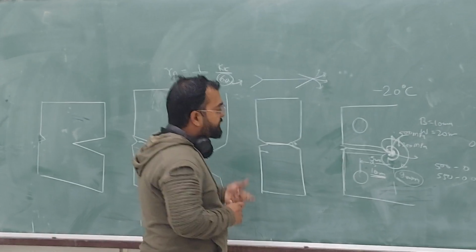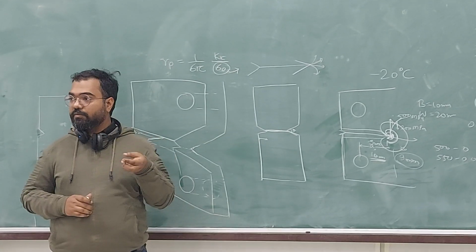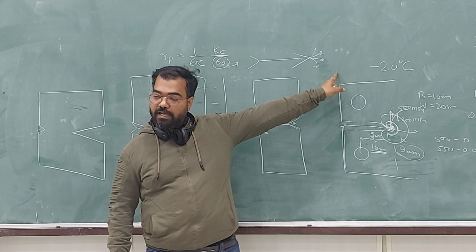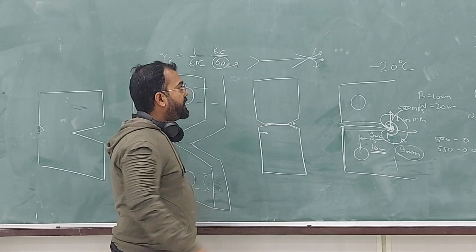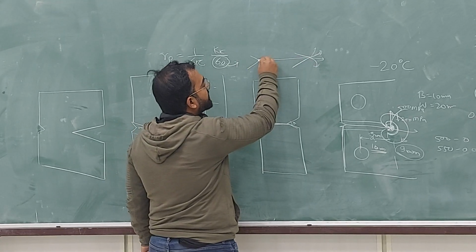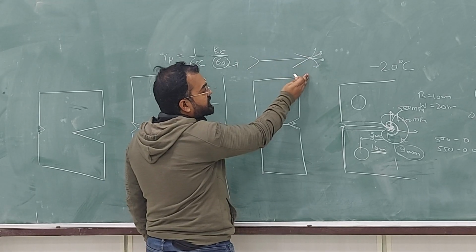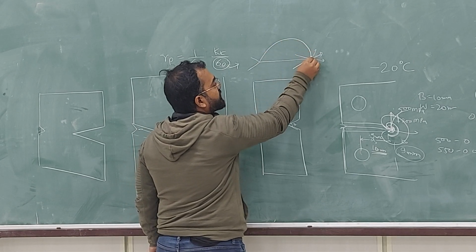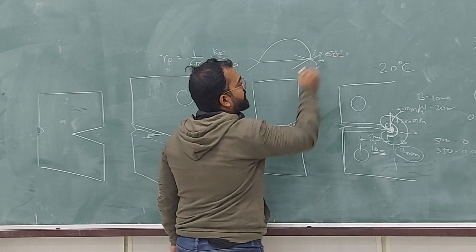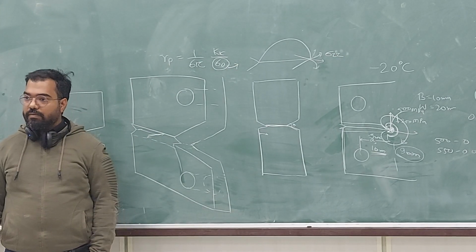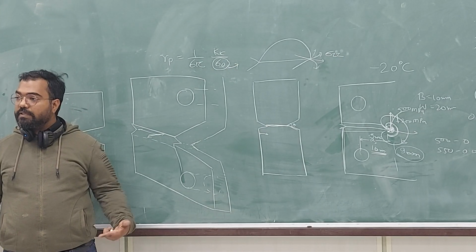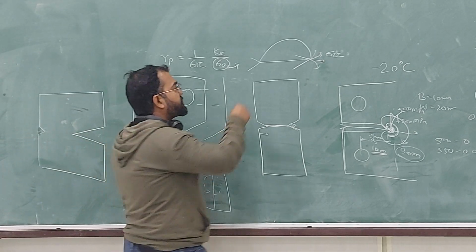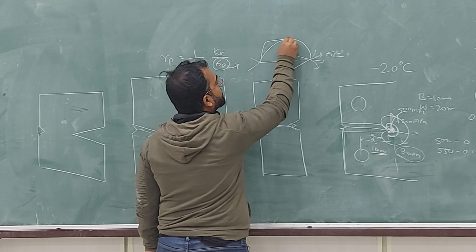So we create this side groove so that we create a plane on which this crack can propagate, because the stresses will be higher. The other reason is, if for some region the thickness is such that you have this kind of sigma z, obviously at the surface it will be 0 and it will be increasing at the center, but if it is really plane strain, it should be something like this.